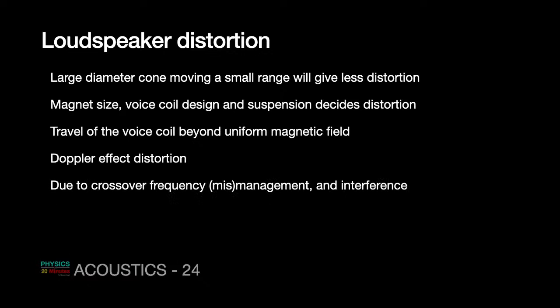Then there could be a crossover frequency mismanagement and an interference because of that. We have just seen that in a multi-speaker system, some frequencies will go to one set of speakers and some other frequencies will go to other sets of speakers. Now if there is a distortion in that frequency management system, some cutoff value has changed, some resistor has failed, some resistance has changed because of temperature, etc., then there could be mismanagement and there could be distortion.